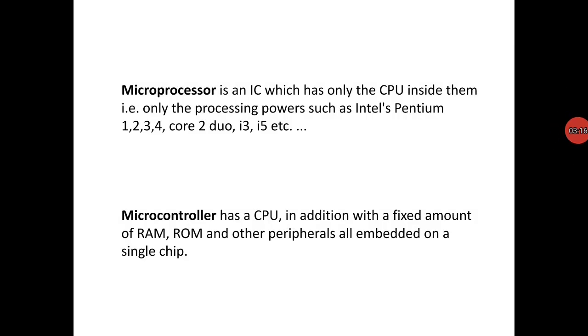A microcontroller is normally used for specific applications. A microprocessor can be used for various types of applications by adding an appropriate amount of memory and input output ports. They are versatile. Since a microcontroller has built-in memory and ports, it is most suitable for applications where cost and space are critical.